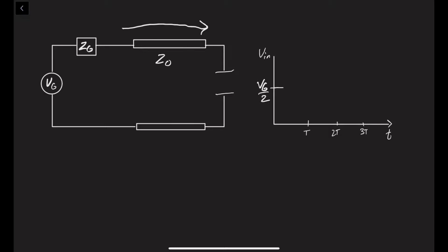Now, if you remember, what happens with a capacitor is that it'll resist a change in voltage. So the initial reflection coefficient will be -1 because it'll be a short circuit. So that -1 will propagate back down, and at time 2t, we will see a short circuit. However, as that capacitor charges up, that short circuit will eventually become an open circuit over time.